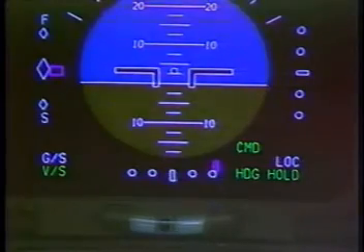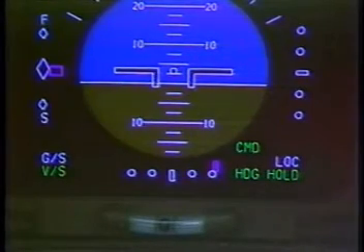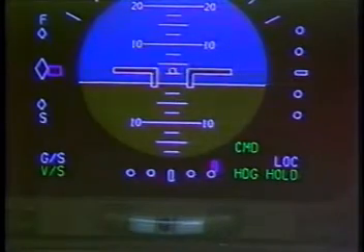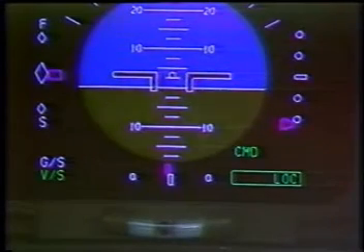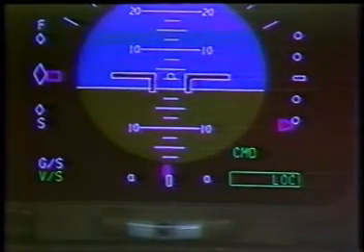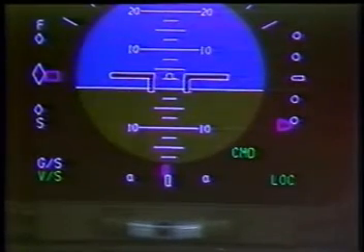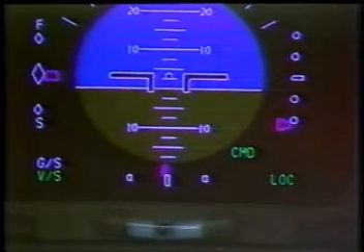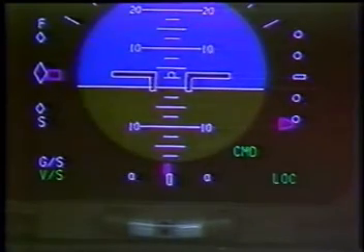Pressing the approach switch displays localizer and glide slope in white on the middle lines of the FMAs, indicating localizer and glide slope as the roll and pitch armed modes. After capture, the color changes to green, and the message is moved to the lower lines, indicating localizer has become the operative mode. Note that when the operative mode changed, a rectangular box appeared around the operative message for 10 seconds. This alerts the flight crew that the operative mode has changed.